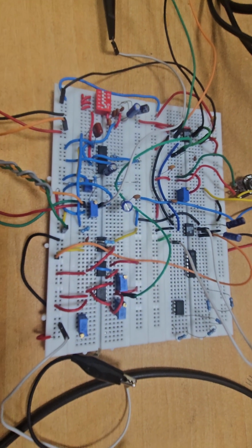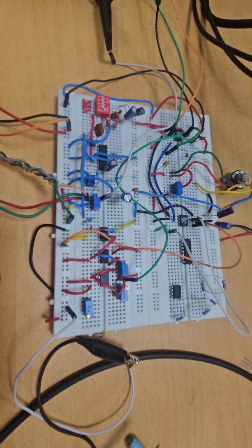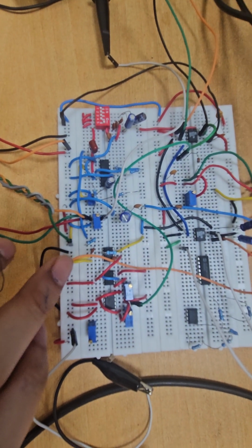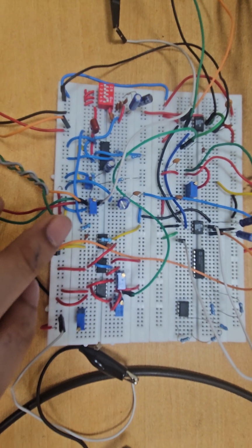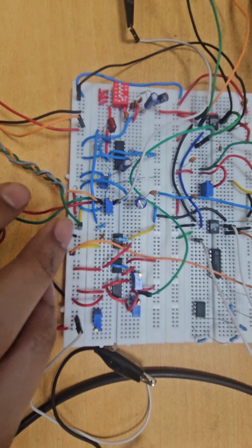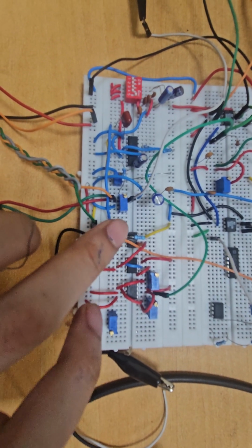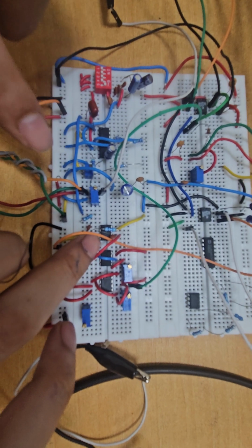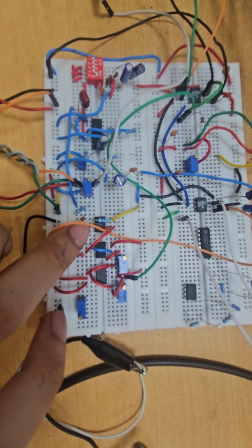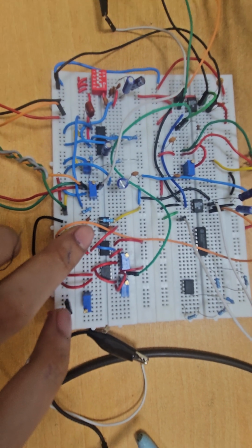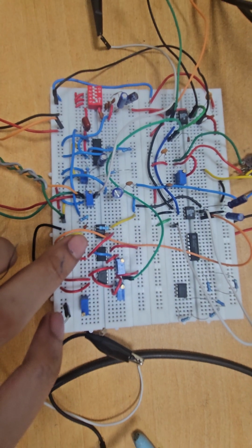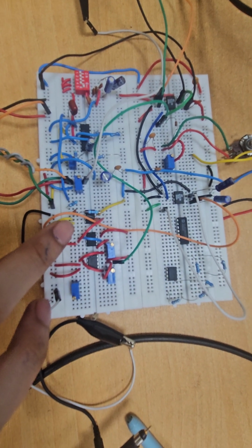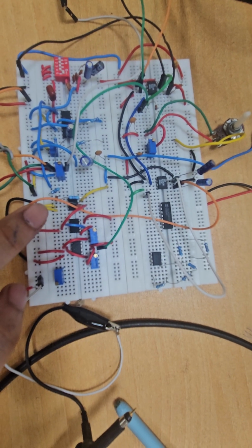Now I will explain to you how the demodulator is working. So I have implemented the limiter discriminator. In this we have first the differentiator. I built the differentiator from a low pass, basically a band pass filter. So it implements j omega around our carrier band, to convert the frequency deviation into amplitude variations.